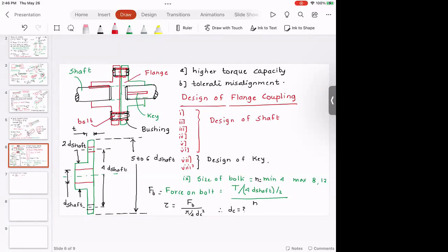And then what you can do is, typically, if you want to add the bushing, the bush would be about typically thickness of 3 to 5 millimeter of some type of soft material. If it's a rubber bushing, it could be anywhere between 5 to 7 millimeter, and you can actually find out the value of the bushing if a bushing needs to be placed to account for misalignment.